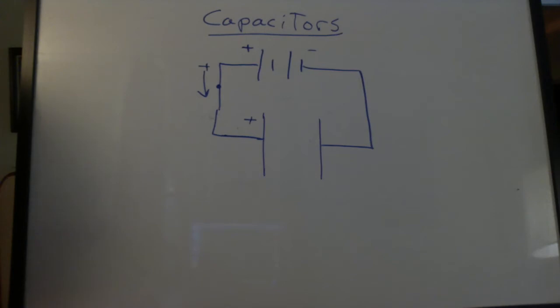That positive charge will now repel a positive charge from the opposite plate, sending it to the battery. As that positive charge leaves the neutral plate, that plate will now become negative. A weak electric field appears between the plates. The next charge comes out of the battery and approaches the positive plate. But there's already a positive charge on the plate now, so the second charge is a little harder to get on there. Another positive is repelled off of the negative plate, making the negative plate more negative.